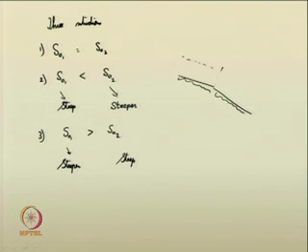So, again the critical depths are same in both, with normal depths below the critical depth. So, you can see that for the more steeper channel, the normal depth line will be above the critical depth line, here it will be less. So, in this case yn1 is less than yn2, in S01 less than S02.